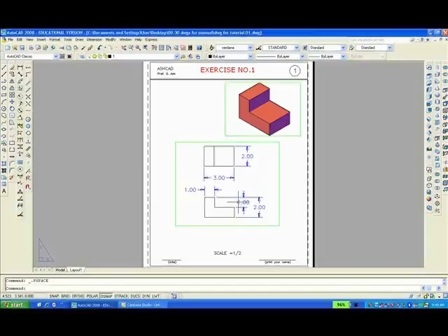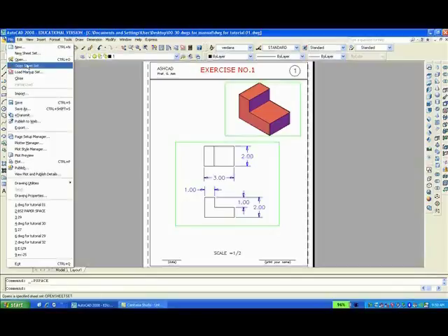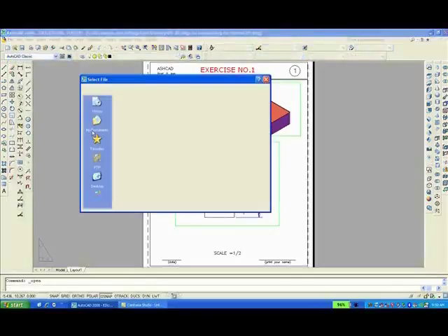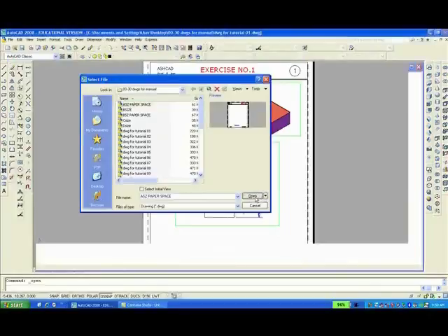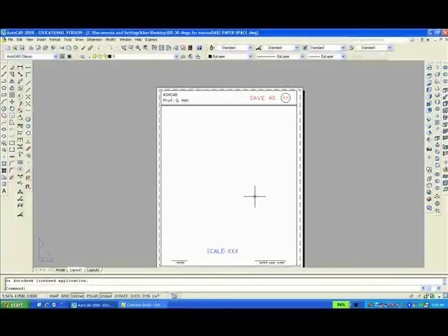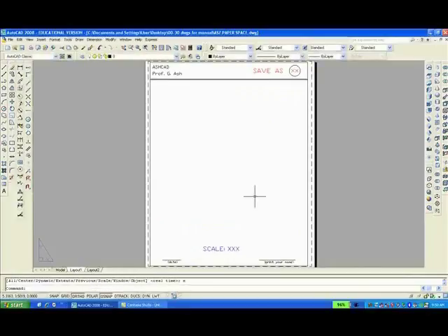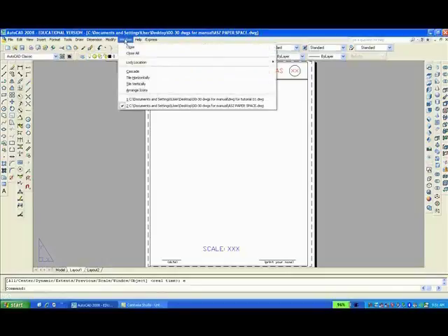drawing. The first thing I'm going to do is to go to File, Open. I want to open a drawing which I created called A-Size Paper Space. You'll be drawing on that mostly. I'll open it. And Zoom extents, Z enter, E enter. Next, I'm going to the window in the menu, and I'm going to tile both drawings vertically.